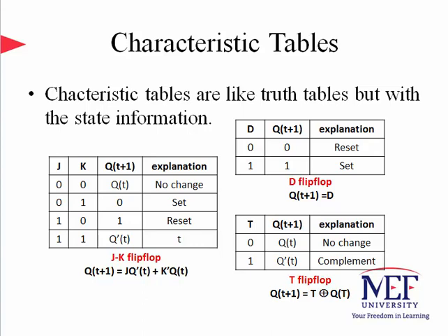Note that T and D flip-flops have 2 rows in their characteristic table, and therefore the JK flip-flop can be obtained by merging these 2 tables, which makes the JK flip-flop, in fact, the most general form of the flip-flop topology we have seen. This discussion finishes our conversation about the memory elements constructed using latches and then flip-flops that are able to hold the states and therefore store bits for as long as needed. Next, we dive into the analysis of sequential circuits.